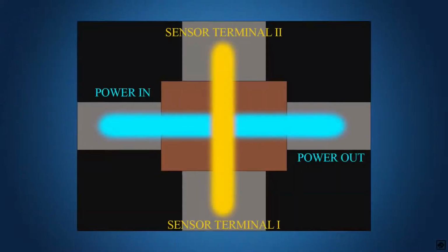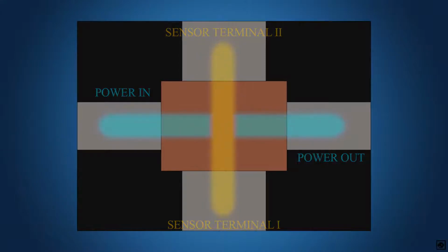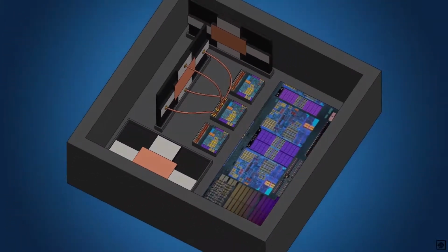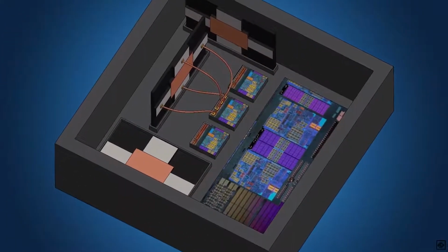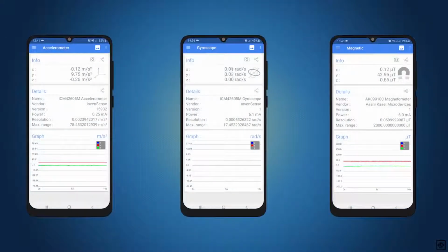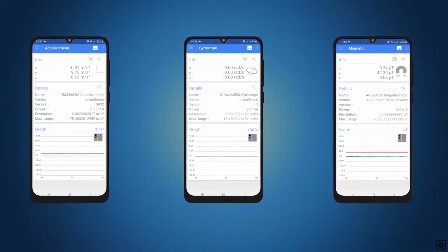Its microstructure looks like this. For using this sensor in 3 directions, we have to use 3 different sensors, all perpendicular to each other. Now with the value of the magnetometer, we detect the direction of the north. Combining the magnetometer data with the gravity and true acceleration vectors, you'll get the full orientation information.